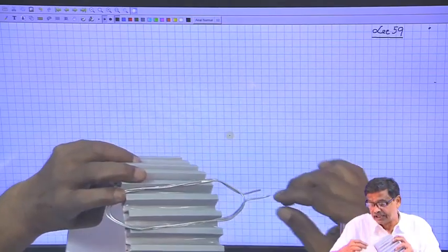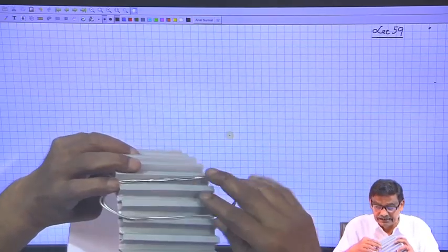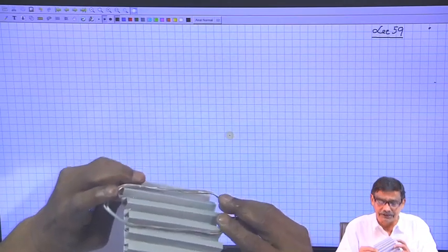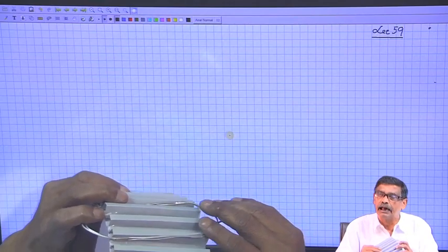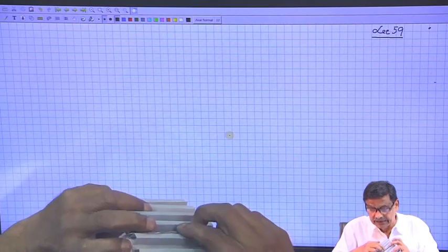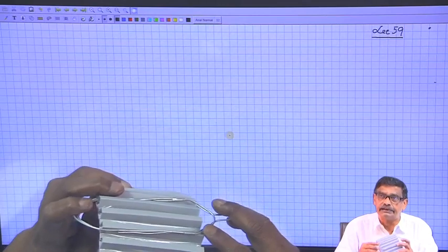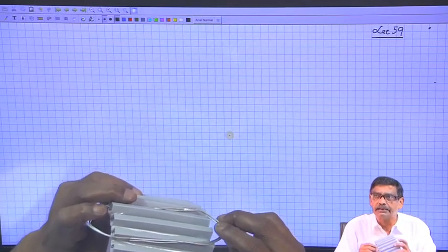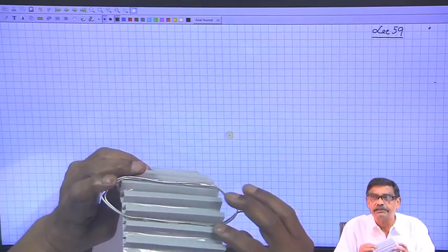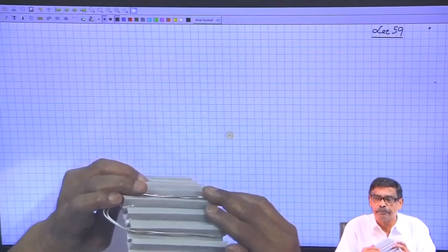If you take a piece of wire, make it like this, on a wooden former, this is to be made, then it is to be placed in the designated slot. You cannot place it arbitrarily, of course, because I have to be very careful to see that the coil span, in degrees, should be 90 degree mechanical, 180 degree electrical, as I told last time, which will ensure that if one coil side is under the north pole, the other coil side will be under the south pole.